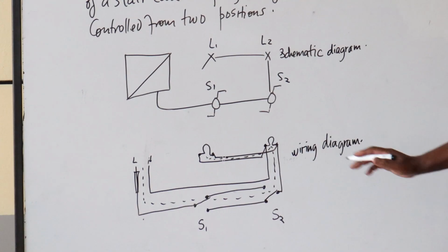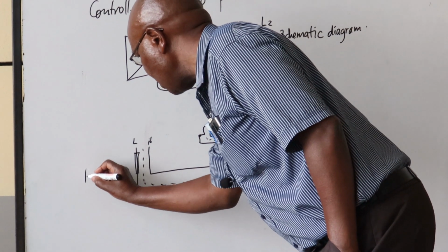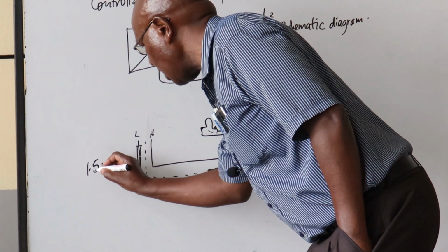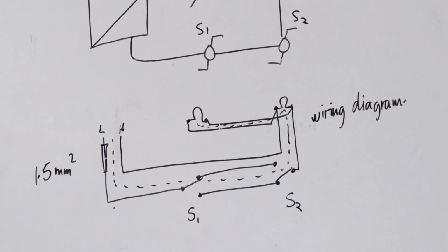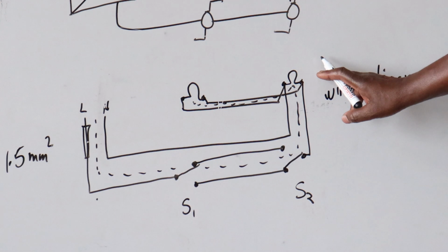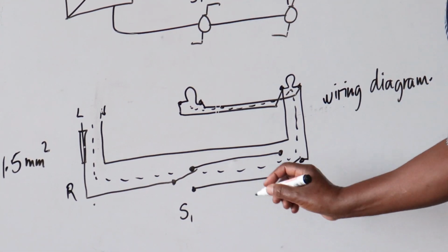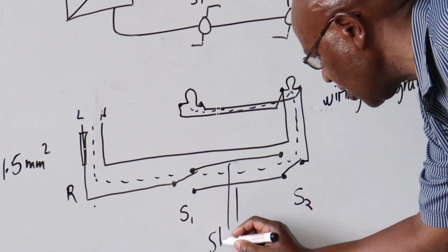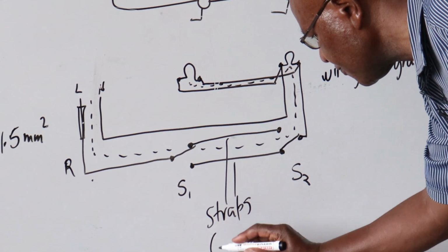At the moment, the cable size currently used in the market is the 1.5. I hope with the IE revised regulations, we might change over to the 1. And then from the live, the cable that is carrying the power up to the accessory is usually color-coded red. Here, we have these 2. These are referred to as straps, and they'll also be red.